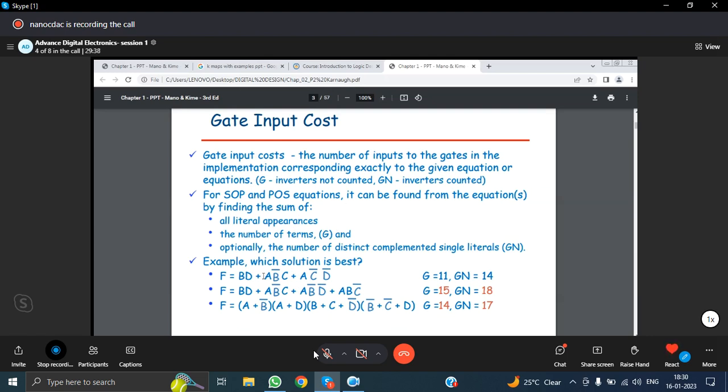So overall, what I want to say is, see these three functions. How many gates do you need for these three functions? Each and every complement requires one NOT gate. B bar, C bar, D bar need 3 NOT gates. Here 2 AND gates are required. Function BD needs 1 AND gate. Here 3 AND gates are required. 3 plus 2 OR gates are required. So 5, and at the same time how many NOT gates are required?